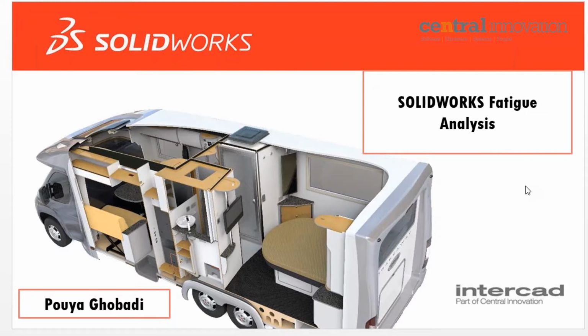Basically, when you apply a load, we know how to do simulation obviously. When you apply a load to a component and you get the stresses for that component, if the stresses are below the yield stress of the material, that particular part is not going to fail. Well, what happens if you apply the same load repetitively to that model? Eventually that part, that material is going to get tired. Cracks are going to develop throughout the model, and eventually fatigue is going to happen.